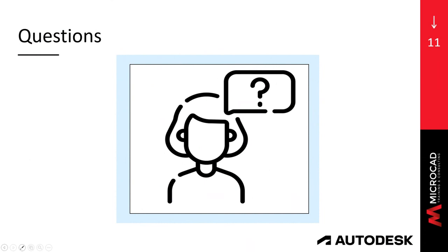So my advice there is always to ask whoever sent you that survey file. If it's a CAD file, they should try to model near the 0,0 location in the CAD file. I don't know how Civil 3D works in that sense, but it should be within a 10-mile radius. So, 10 miles is a huge distance. And that is your playground. So you can be 10 miles away, one from the other, and you're still kosher.